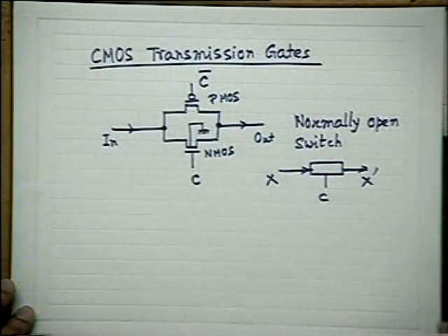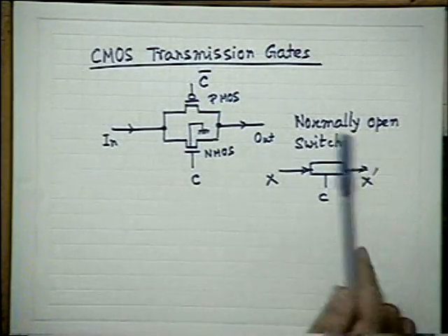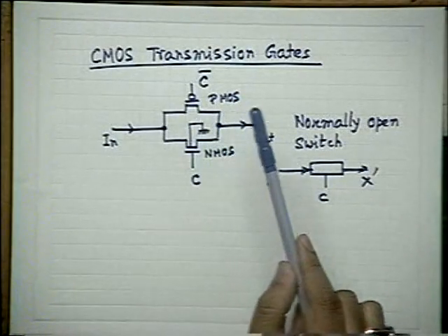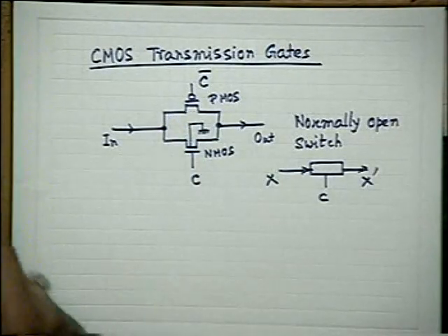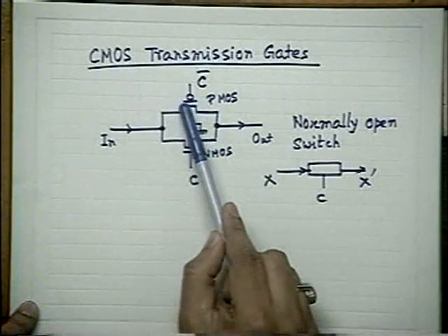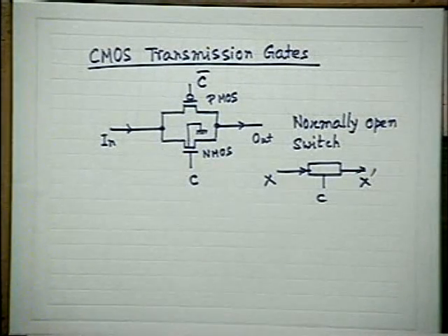But what about the PMOS? In certain designs, this can be kept floating. And in certain other cases, the so-called source, one of the two diffusions, is connected with the NWell, which I have shown when I discussed the NWell construction, very clearly. So this may be connected either with this side or usually it is connected with this. I'm not showing, but it can be kept floating also. There are various designs. The substrate has to be kept grounded from noise point of view. Substrate should not be kept floating. It should be grounded. At least there should be a very good AC ground for the substrate. Otherwise, there will be floating noise. So this should be kept in mind.